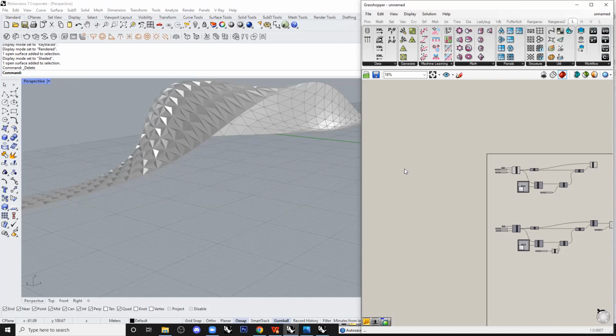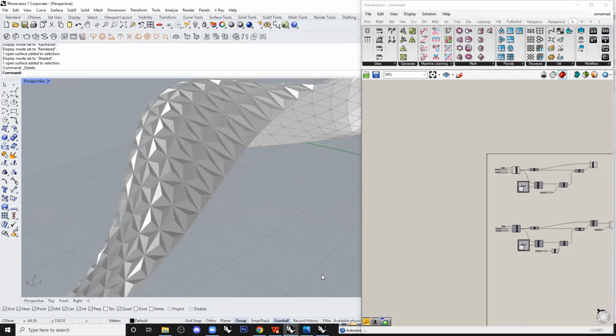How to create voids in the pattern. You need to create an algorithm for that. So in the pattern, if you want some voids, it depends how you want to do it. So in a prism, there are like 1, 2, 3 faces. You can delete a few faces. It will create a void. Or what you can do is you can scale the faces into smaller sizes and make these scaled pieces a void, like you can trim it on the prism. So it depends on how you want to create void. You need to use algorithms to achieve that.